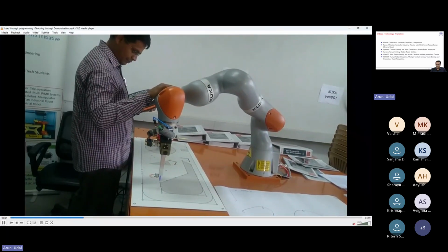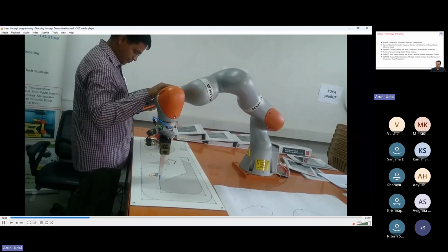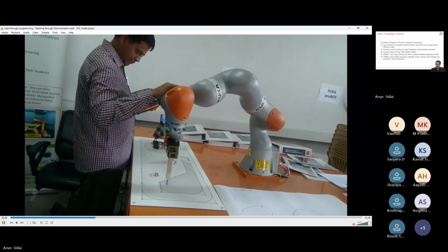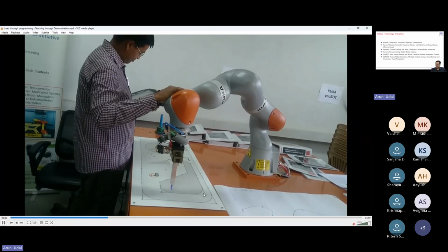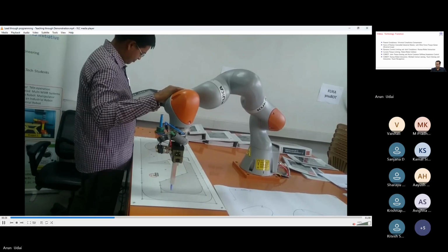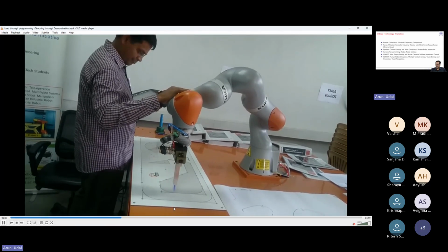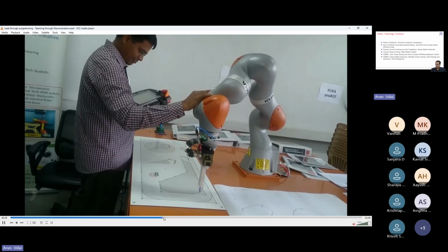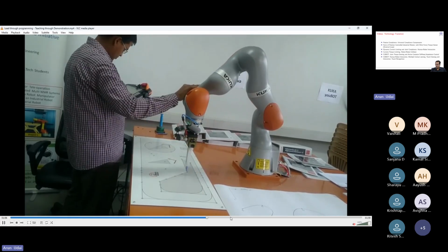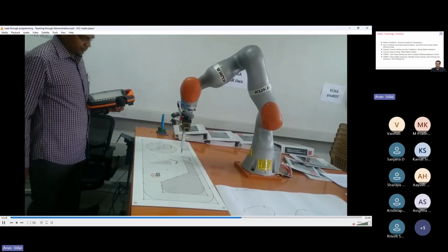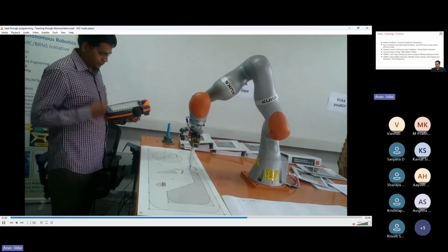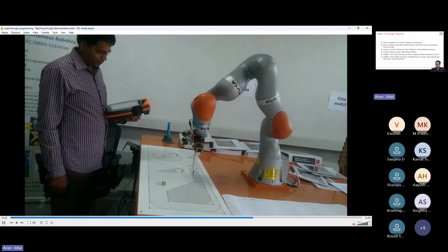The previous video was from KUKA, Gurgaon, the KUKA center. They have a training center there. So I am taking it to different locations one by one, teaching those locations. At the end, I have just left the robot and asked it to repeat it. This is known as lead through programming, teach and repeat kind of.